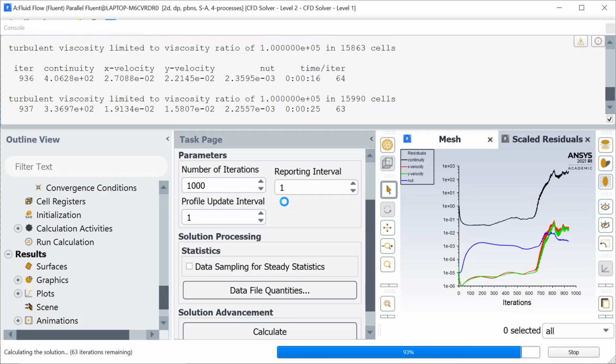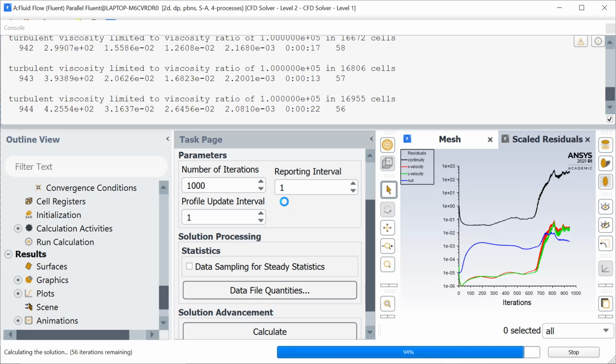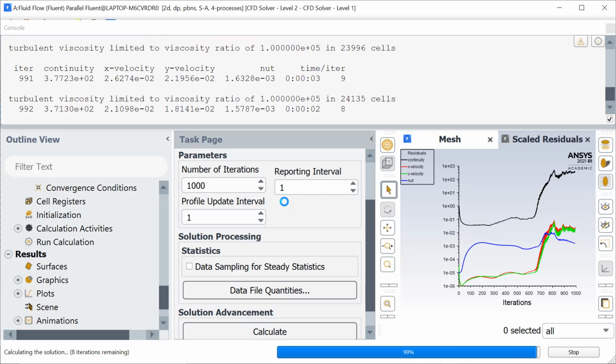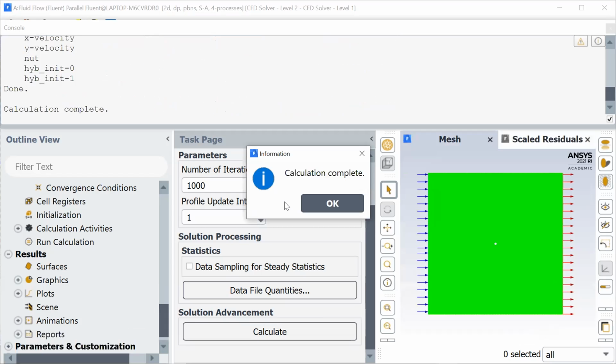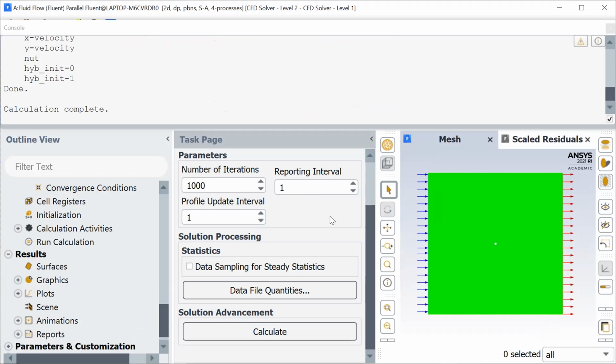We're getting a lot of variation in the results. So we're going to see what the results look like. They may not be super accurate, but you at least get a vision for the process of how this is supposed to work. And also another option could have been we could have made that mesh a lot smaller. A lot of times a more rectangular mesh where it's not quite as tall can be good. But our calculations are complete, so let's take a look at our results.